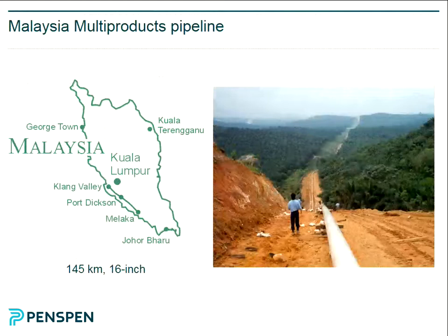Going down to 2,000 meters, but actually it's fairly straightforward from a process point of view. The challenge here is materials and construction in very deep water. And actually, there were some issues with concern about hydrogen sulfide in the soil as well. They were worried about stress cracking, corrosion on the outside of the pipeline. So the least of the worries really were process on this particular project.